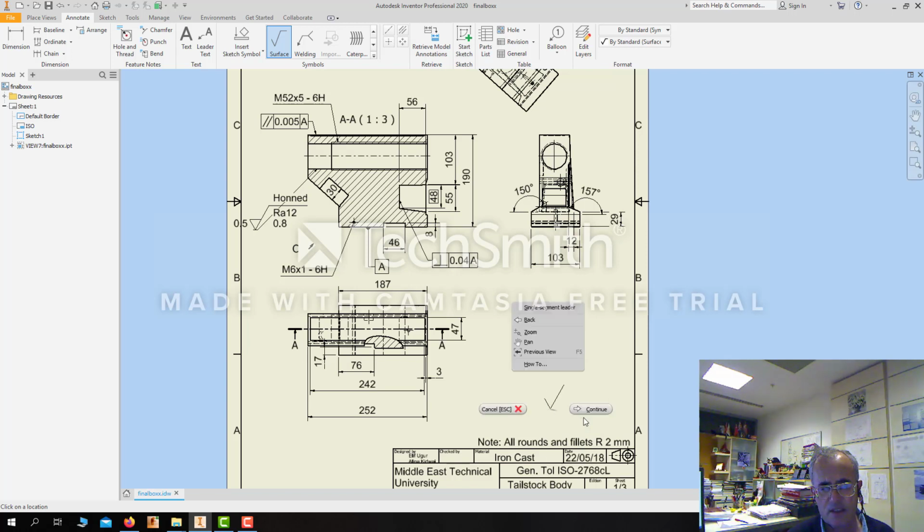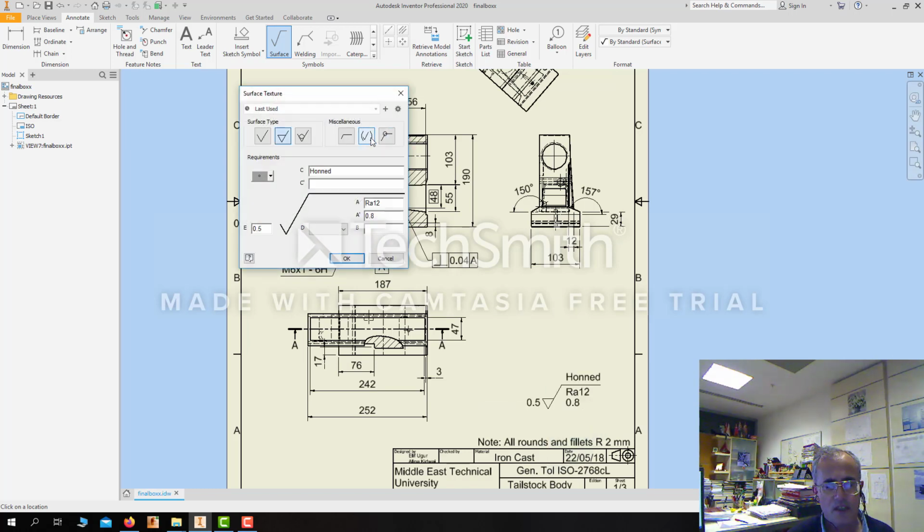Right click the mouse, and then say continue. Clicking on this will give the main symbol in parentheses. It is to say that except for the individually indicated surface, for all the other surfaces, the arithmetical average roughness height is, let's say, 40 micrometers. Well, for all the other surfaces, there is no need to mention the cutoff value.